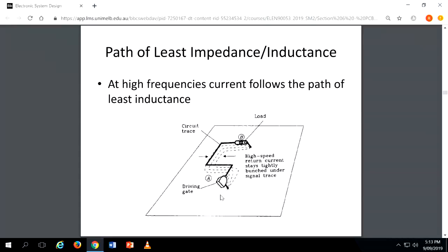Maybe I will recommend auto routing once AI is introduced and takes care of your design needs. But during this time, once I used auto routing, it made a big mess when I had digital and analog. You can use auto routing for some simple circuits, because that is easy to route. One of the places auto routing will mess up is these high frequencies.